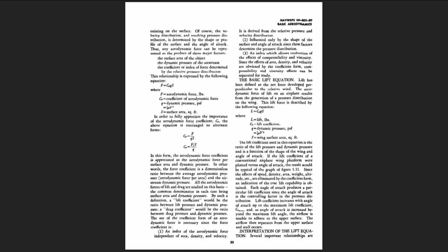2. Influenced only by the shape of the surface and angle of attack, since these factors determine the pressure distribution, and 3. An index which allows evaluation of the effects of compressibility and viscosity. Since the effects of area, density, and velocity are obviated by the coefficient form, compressibility and viscosity effects can be separated for study. The basic lift equation.